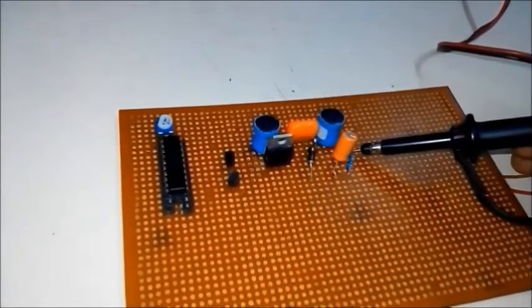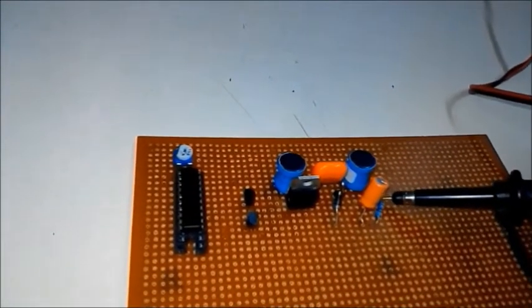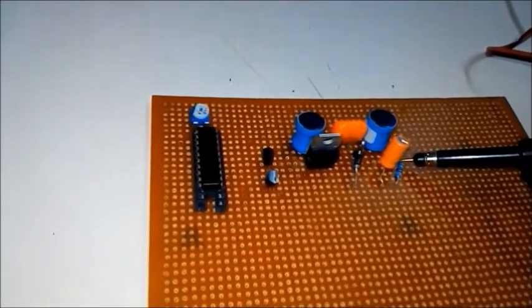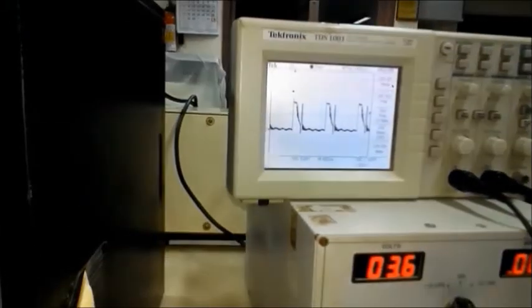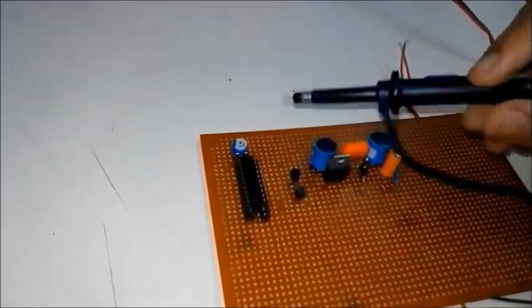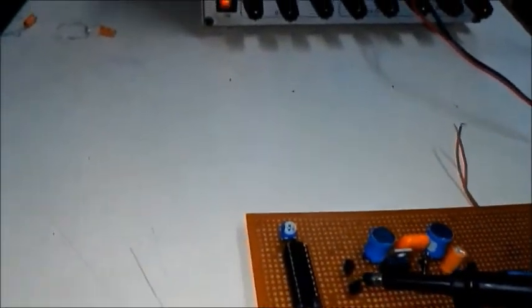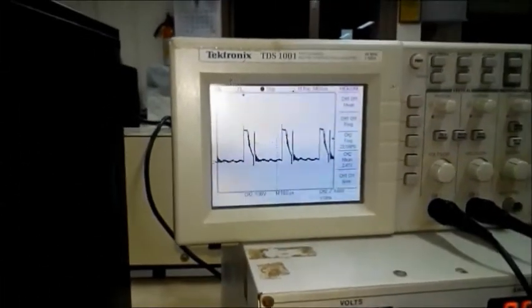Next comes the buck boost converter circuit, which has the output voltage either greater than or less than the input voltage. It is essentially a boost converter followed by a buck converter with a capacitor to couple the energy. A feedback from the output is given to the input of the ADC. Output of the ADC is used to generate the PWM. Duty cycle of the PWM is controlled by the ADC output.